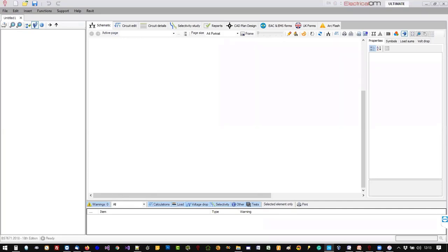So in there, when you're filling out, you can produce something like an EICR, but you don't have to complete test results. So you can build your network, you can build your schematics, get the data from various distribution boards and final circuits in there as you wish to do so, and then import that straight into ElectricalOM and carry on with the design from there. It doesn't physically require you to input test results to get that data back into the core software.